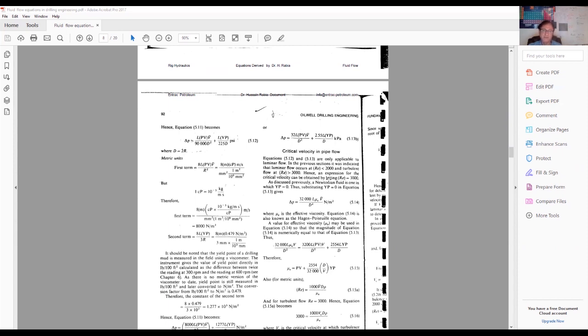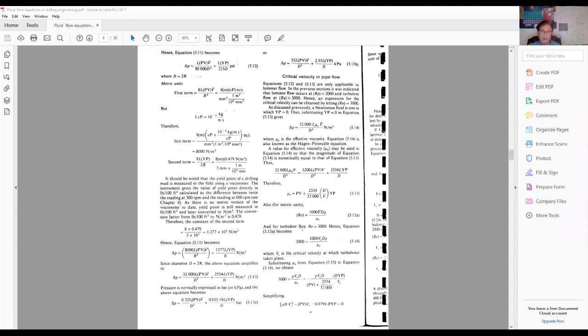But because Reynolds number is cumbersome to use, what I decided to do is to use a critical velocity, because in drilling we always calculate velocities. So my principle here is to find a velocity that causes turbulent flow, and I called it critical velocity. Okay, so I go back to Reynolds number and say, what is the critical velocity that will cause turbulent flow? So in this case, I need to make an assumption, what value of Reynolds number?